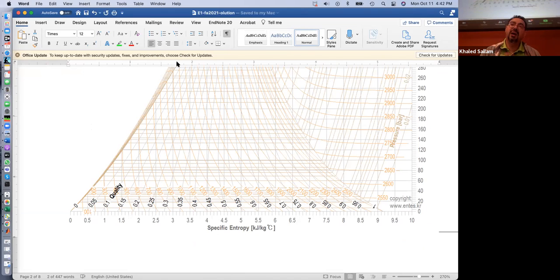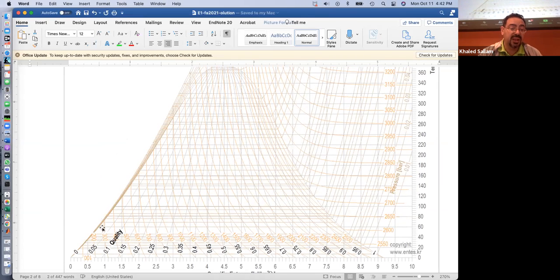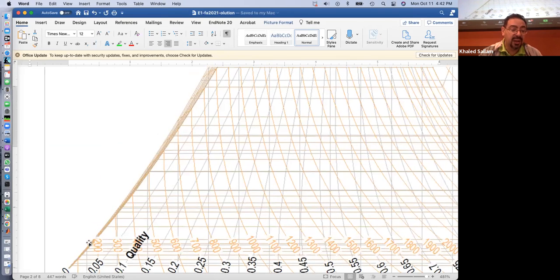That's okay for a cartoon when you're trying to say here is the pump, but when we are actually plotting it on this actual TS diagram, the pump will show up as what? As a dot. The pump will show up as a dot at 50 degrees C, because where it will go is to nothing, right? And I want you to see this and remember it. When you take 4263 and you see them neglecting work pump, you will understand.